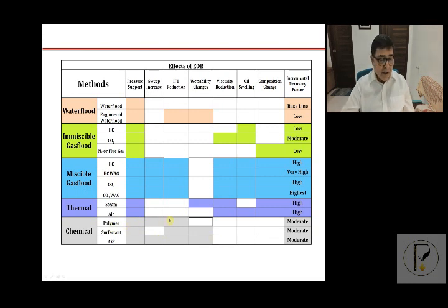Chemicals, yes, it's coming up very fast, very quick. What it was 30 years back, today it's totally different. The cost has gone down significantly, and polymer not only modifies the flood front, not only makes an unfavorable displacement favorable by increasing the denominator of the mobility contrast, it can even reduce residual oil saturation.